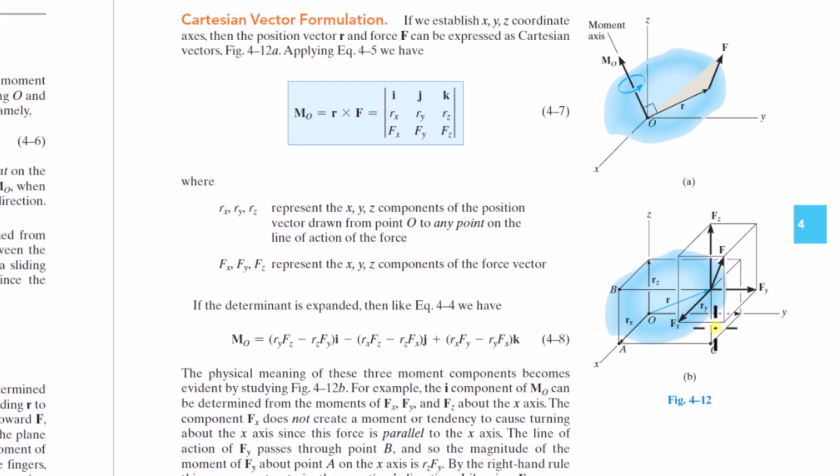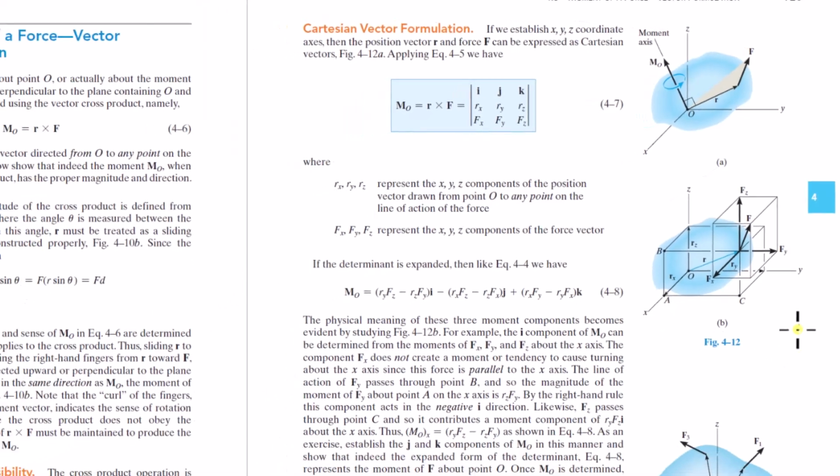If you use the right-hand rule with the curl, with the thumb in the direction of positive z, that's a positive rotation. So this is positive. Minus Ry, Fx. Yeah, so Fx, Ry. And that's negative, right? That's causing a clockwise rotation if you're looking down the z-axis. So it's negative. And then Fz causes no rotation about the z-axis. So, okay, we talked about a lot of this in the previous two videos.